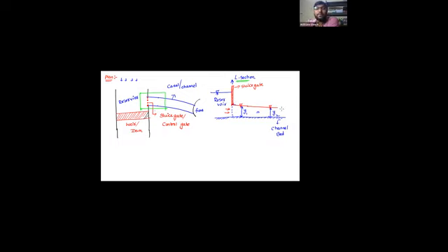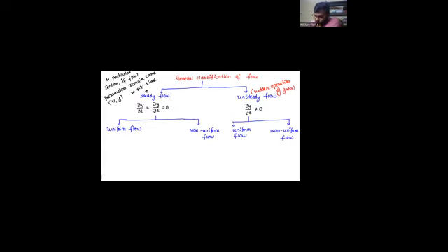So now my dear, what is meant by uniform flow? The meaning of uniform flow is ∂y/∂s = 0. What is the meaning of ∂y/∂s? It is the variation of the depth of flow with respect to space. This is a steady flow. Now this is going to be with respect to whom? With respect to space. If flow parameters remain the same, that's going to be uniform flow.